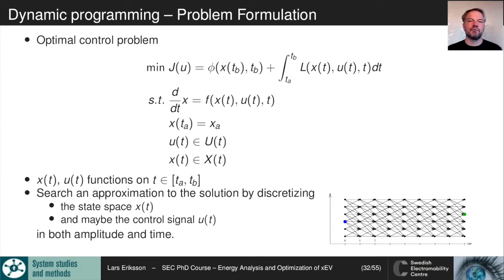The most straightforward thing is that we can take electrical energy while we do the regenerative braking, and we can use that energy we got there during the next acceleration. Or the other way around, if we have an acceleration, we know that sometime in the future I might need to brake. So then I use a little bit of energy and recover that energy in the next deceleration. When we have done this, the result is a combinatorial problem.